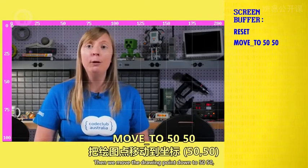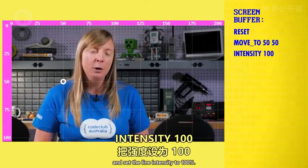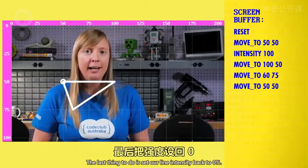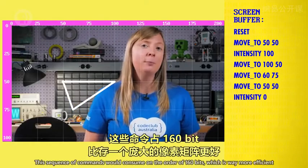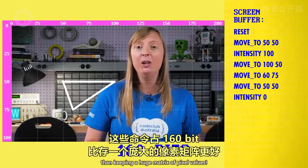Then we move the drawing point down to 50,50 and set the line intensity to 100%. With the intensity up, now we can move to 150, then 60,75, and then back to 50,50. The last thing to do is to set our line intensity back to 0%. Cool, we've got a triangle. This sequence of commands would consume about 160 bits, which is way more efficient than keeping a huge matrix of pixel values.